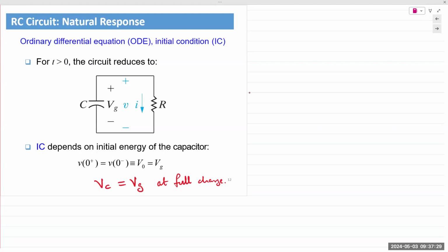Okay. Current through an inductor and voltage across a capacitor cannot change instantaneously. Energy transfer cannot take place at the snap of a finger, right? And so you have to look at the circuit prior to the switch being flipped. That will allow you to set up the initial values for your analysis. Questions?